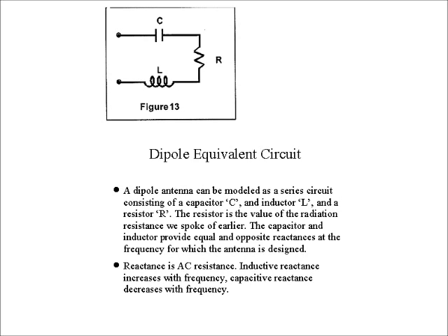You can't even see it. There's a little tiny surface mount resistor in here, which I'll guarantee you can't see. And there's a little capacitor in here that I can tune so I can make things go up and down. As soon as we finish the slide thing, we're going to fire up my vector network analyzer, and we're going to look at my 40-meter antenna and see what goes on.